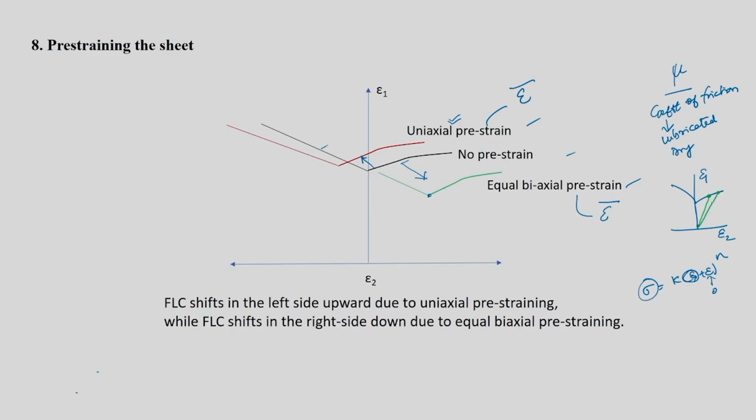So basically it is changing the strain path from one beta to another beta rather than the forming limit itself. Your epsilon 1 change will get adjusted with respect to the change in epsilon 2, and accordingly you will get the limit strain. Individually the limit strain may change, but it will finally lead to the same forming limit. That is why we always say that the forming limit is a material property. So that is the effect of mu. There is a lot of discussion in the subject about the effect of mu, but in general this is the way it is going to work.